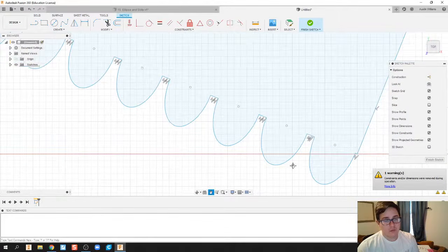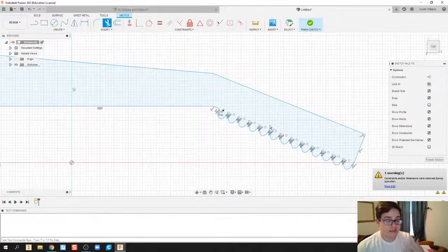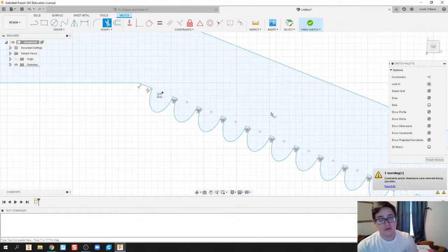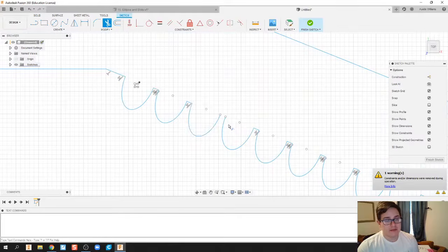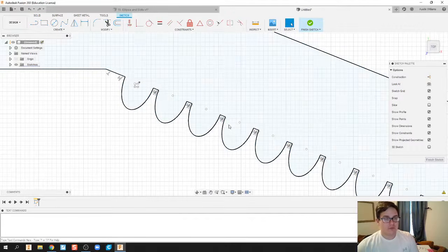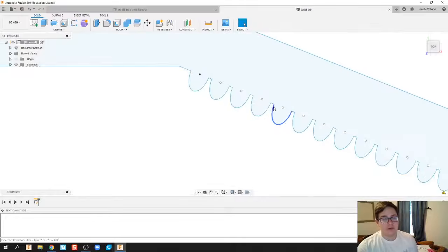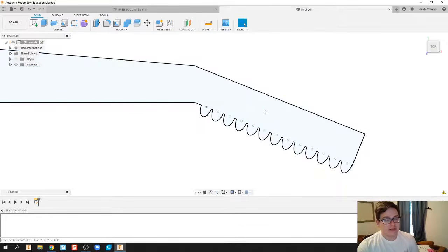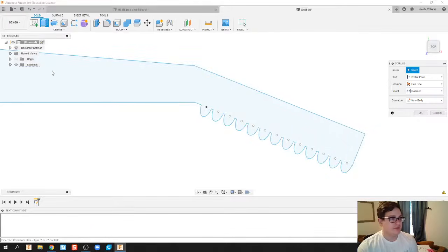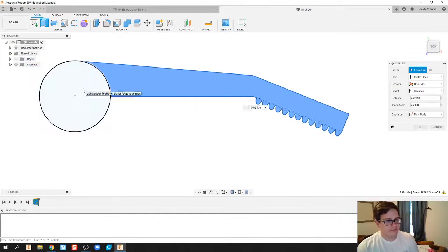And there we go. We know I haven't messed up my sketch so far because that infill area is denoted as one solid piece of geometry. And so if I were to trim a piece, like let's say right here, even if I don't know where that piece is missing, I can know for sure that if I were to try to extrude this or do some sort of revolve feature, something wouldn't work. So when you are using your extrude commands or anything similar, make sure that the inside area has that light blue shade to it. So now I'm going to go ahead and extrude this.